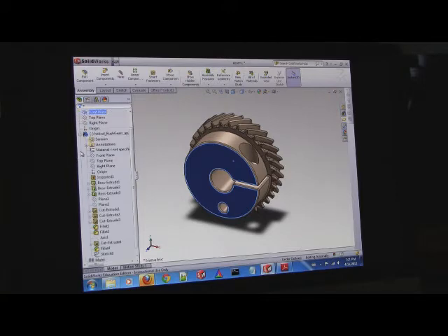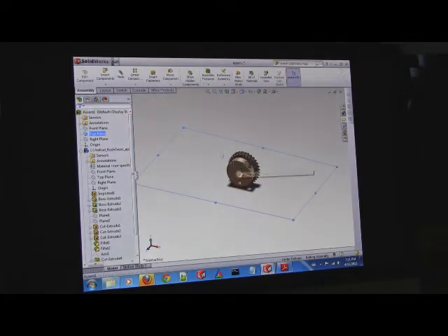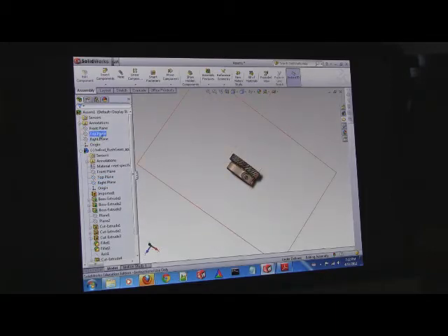Okay? Things get weird when your parts don't align, at least any of them, in terms of their planes within the assembly plane. So let me explain that real quick. Everyone see my screen? These are the assembly planes. Okay? And now under my part, I have my part planes. They're different. We should align them. If I look here, I can click on two of them. See how my two front planes, my part and my assembly plane, are completely different? Usually you want to align this stuff just to keep it safe.